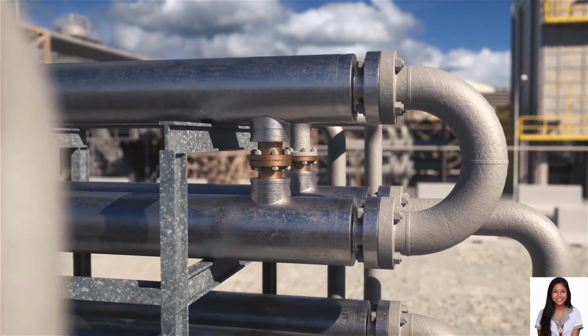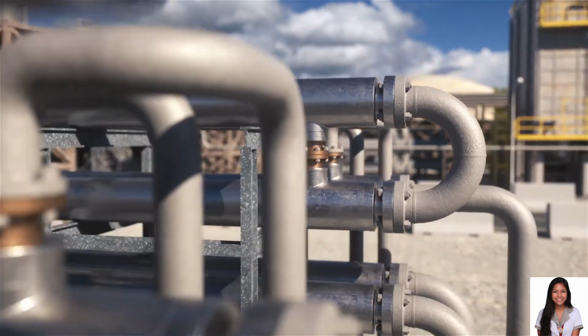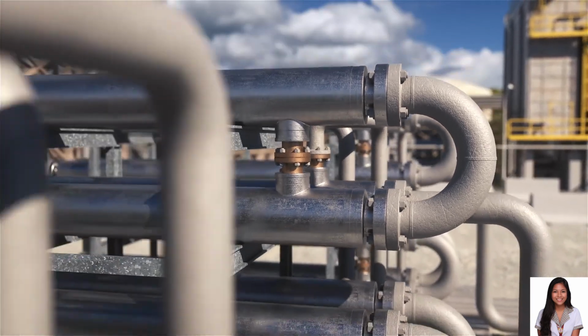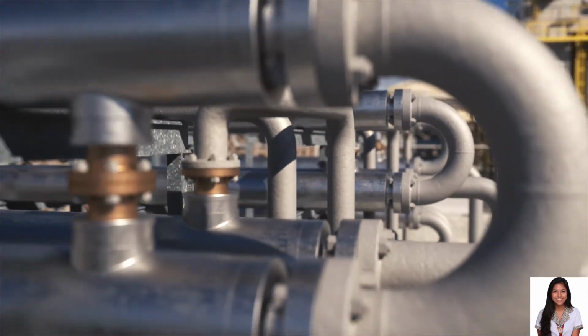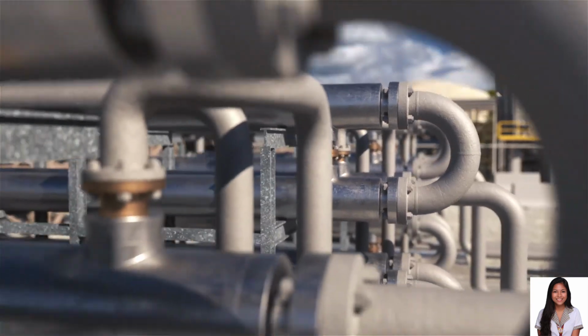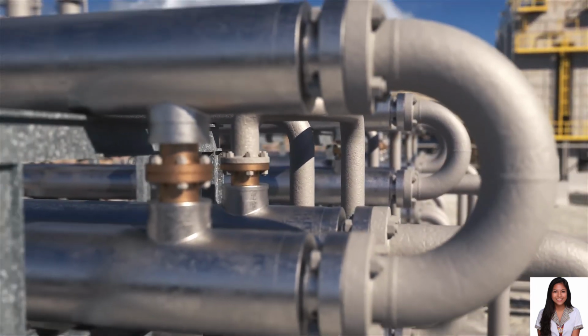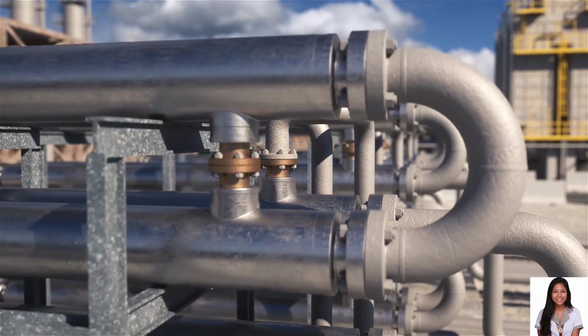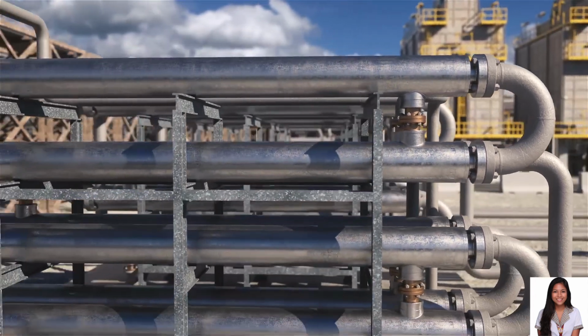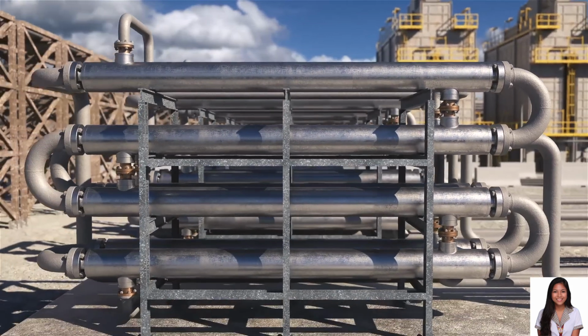Now remember, whether parallel or counterflow, heat transfer within the heat exchanger involves both conduction and convection. One fluid, or the hot fluid, convectively transfers heat to the tube wall, where conduction takes place across the tube to the opposite wall. The heat is then convectively transferred to the second fluid.